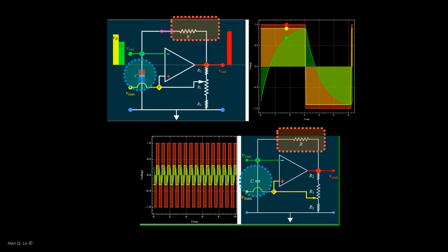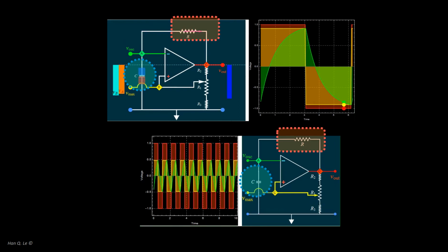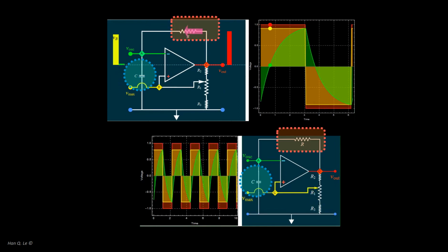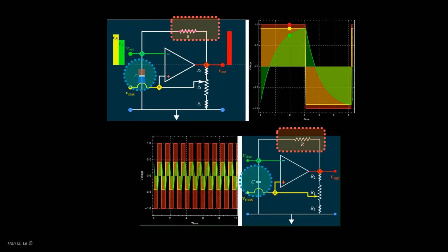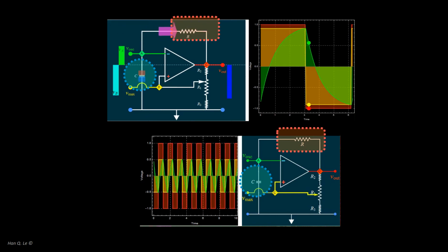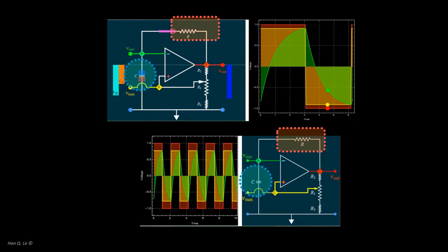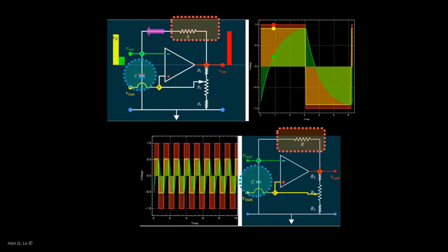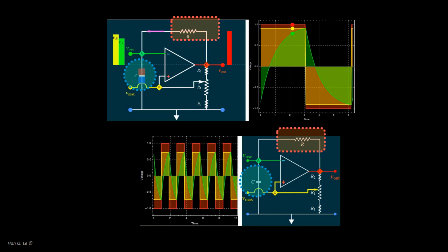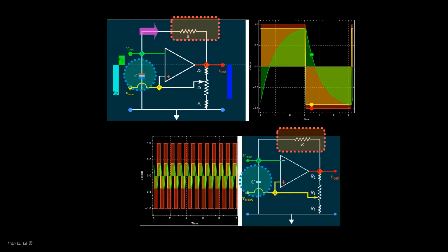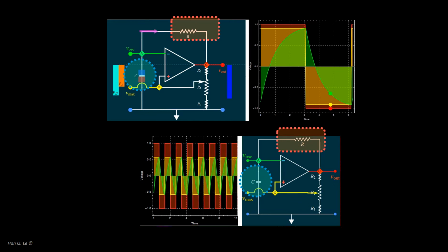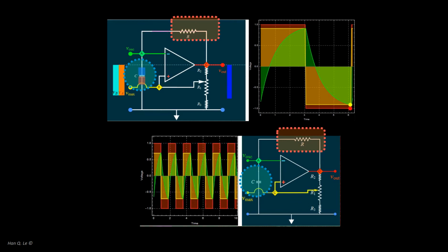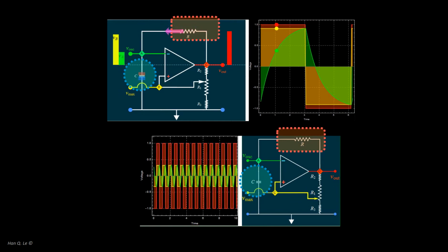How fast it vacillates back and forth depends on the time it takes to fill the capacitor to the level of the non-inverting input. The bottom graph shows how the oscillation frequency can be varied by changing the required fill level of the capacitor. Alternatively, the feedback resistor can also be varied to control the frequency. However, the circuit is sufficiently complex with one potentiometer. Rather than using two potentiometers, the feedback resistor can be changed manually.